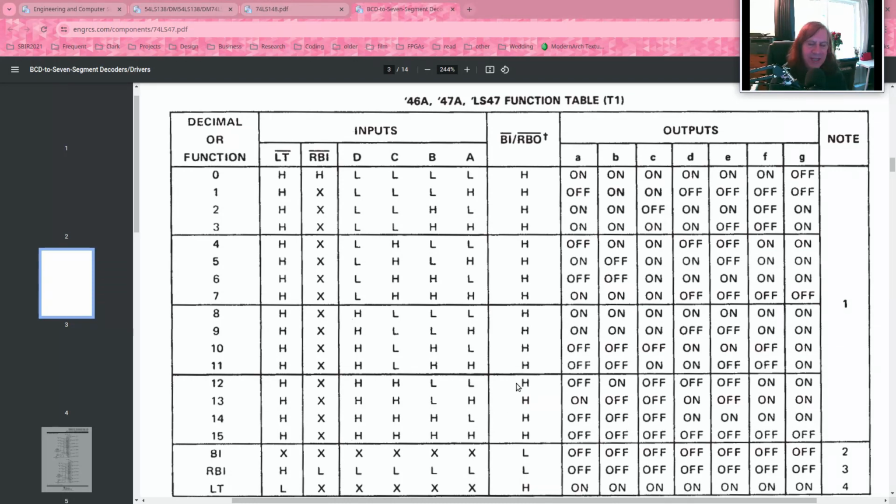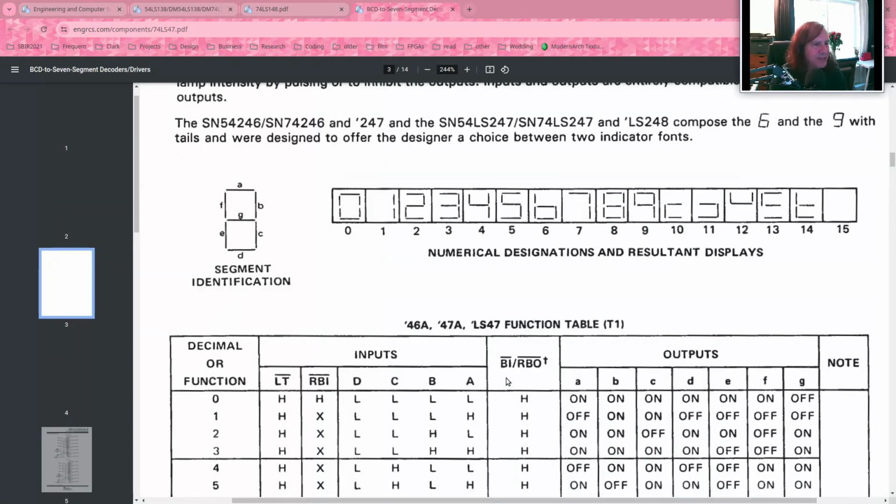And when you do that and you minimize and you come up with your equations, here's what this 7-segment display looks like for each of your inputs. For 0 through 9, you get these digits 0 through 9. For 10 through 15, you get strange things, right? This is not a digit. This is not a digit. This is just what the circuit that they implemented happens to display for 10 through 14, and 15 comes out completely blank. That was probably a design choice.